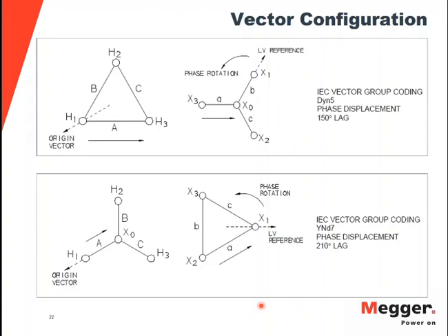Other than that, you cannot really see if the unit is properly discharged after any saturation procedure. Anytime you apply a DC voltage, you're creating some energy on the windings that you would like to discharge. You don't want to be the path for that discharge energy. So better to have the equipment. There are some old suggestions on the battery side, but I think that nowadays we have the technology, so let's use the technology available nowadays.